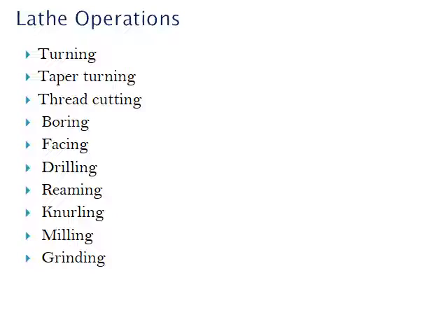That is why it is called swivelling the compound rest. You swivel the compound rest, for example to 6 degrees, 7 degrees or 8 degrees, and set it accordingly. Then you can start the work, and the tapered surface can be produced. This is a simple mechanism. Next we can go to the thread cutting operation. What is the thread cutting operation?